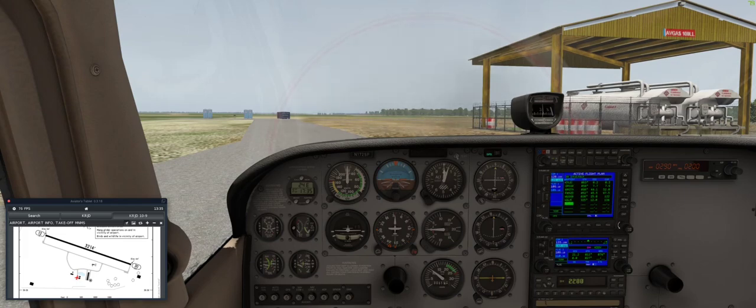It would be a blank one like this, and as soon as you hit this smaller knob, it takes you into the mode where you can pick the waypoint name and put it in. That's all I've done. Now, a few things to be aware of: when you see this is highlighted, that means the outer knob is going to move to select these waypoints so you can manipulate them. If you use this smaller knob, whatever line you're on, it's going to get you into the edit mode of that waypoint, which you don't want to do.